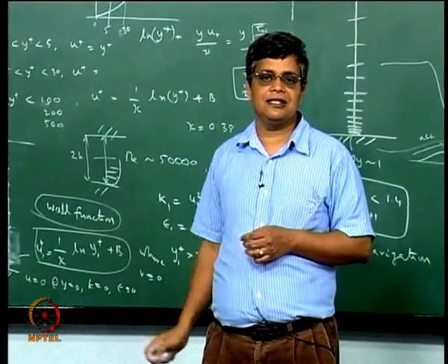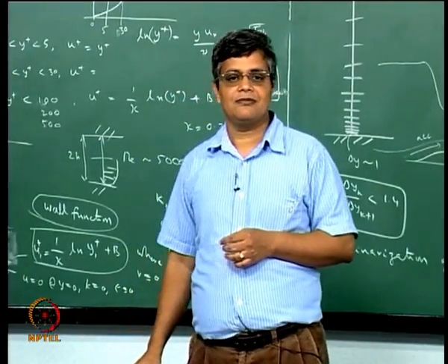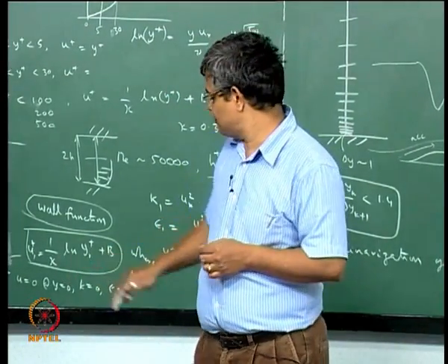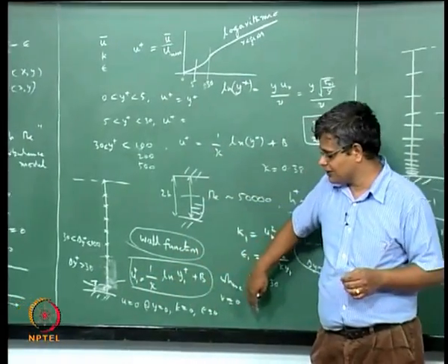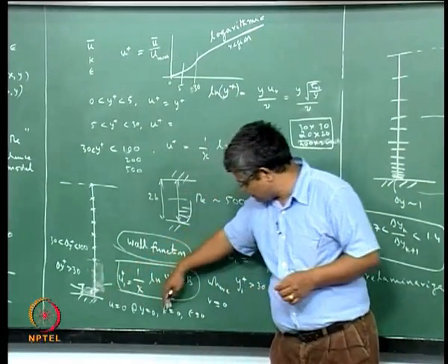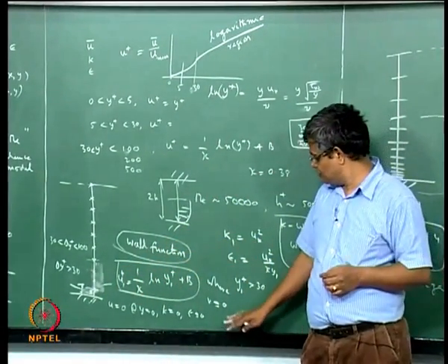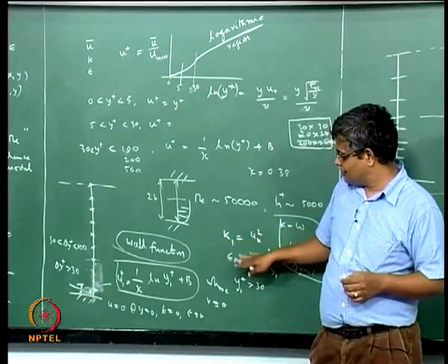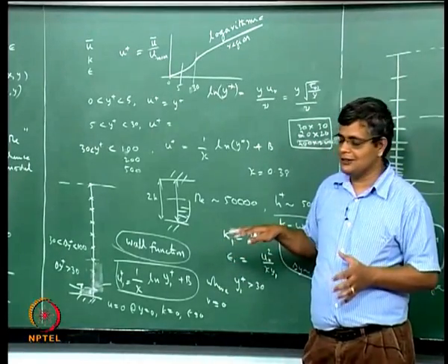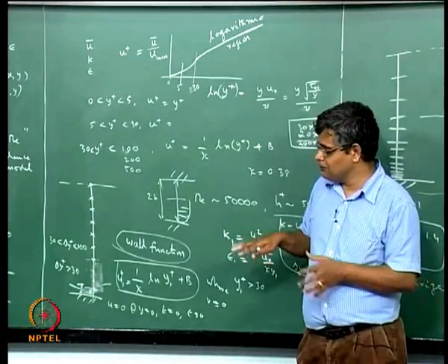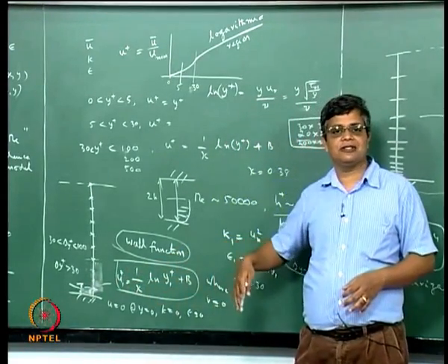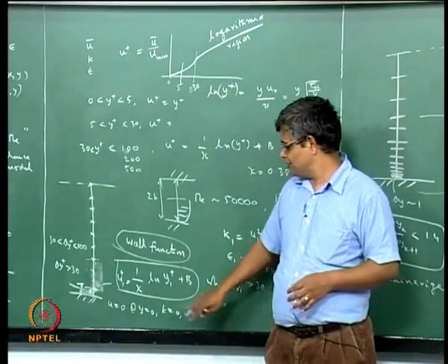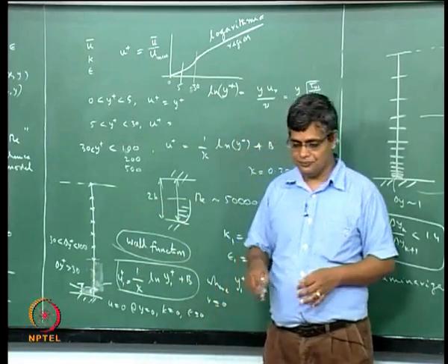One deficiency is the near wall treatment that we have seen, and that is that we have to make use of the wall functions, and that we cannot make use of the natural boundary conditions that at the wall we have k equal to 0 and epsilon equal to 0, but we have to impose a certain non-dimensional variation close to the wall in order to get a solution.